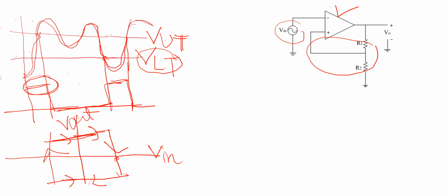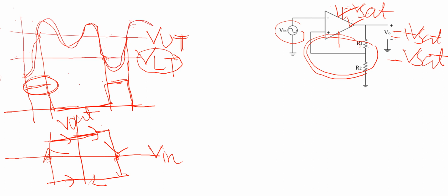So this voltage is the upper threshold voltage and this is the lower threshold voltage, and this is the transfer characteristic of our Schmitt trigger circuit. Now go back to the circuit. So since we have given a positive feedback, output will continuously grow and it will grow until the voltage is positive V sat or negative V sat. So the saturated voltage will be the voltage we are giving for the biasing. Suppose it is minus V sat and it is positive V sat.